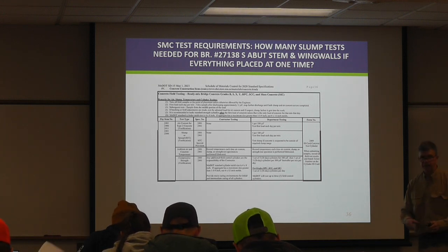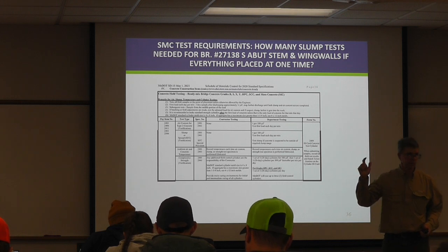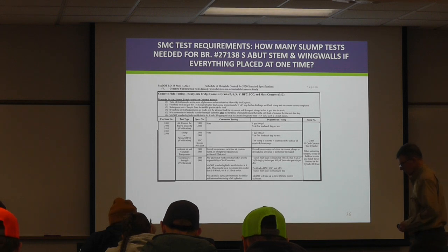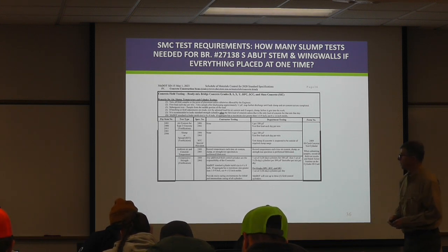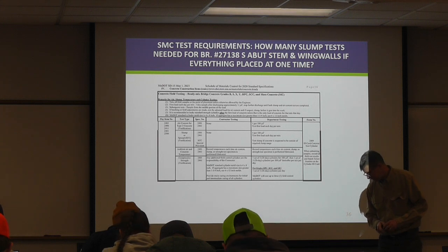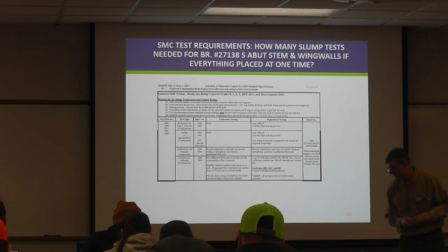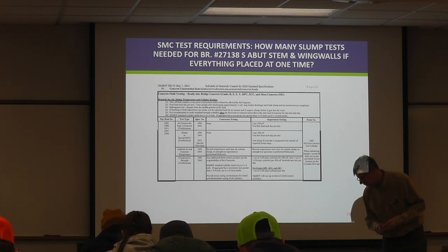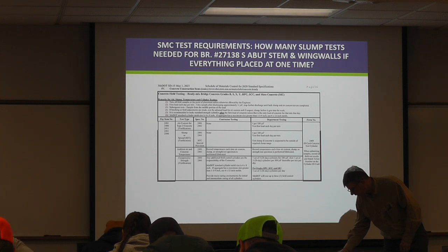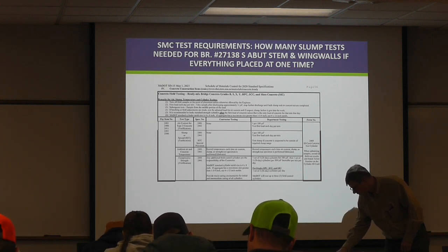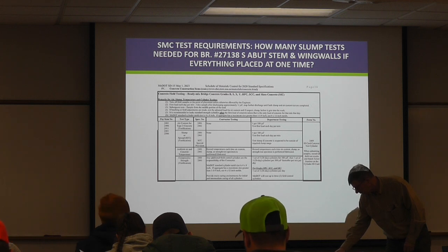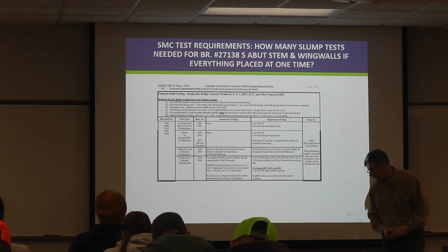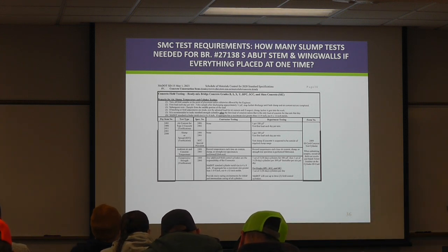Okay, anybody find what type of concrete we have for stem and wing walls? 3B52, very good. So we have 3B52. 280 yards, where do you find that? Page 20. There's a little summary of quantity chart in the upper right, the north and south abutment. You look for structural concrete, 3B52. It's the second line down, and it says 280 under south abutment. The column for south abutment is 280. Okay, so that's some of the parameters you need.